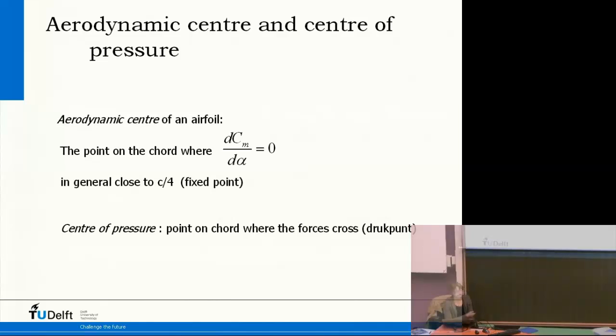Then the center of pressure, and that's the point on the chord where the forces work. So center of pressure is the point where the forces act, and aerodynamic center is the point where the moments don't change with the angle of attack. You can look in Anderson, there are some stories about how this is applied and used in airfoil design. At the moment, for the aerodynamics, we will not continue with this, but you will get it back, for example, in stability and control, flight mechanics.